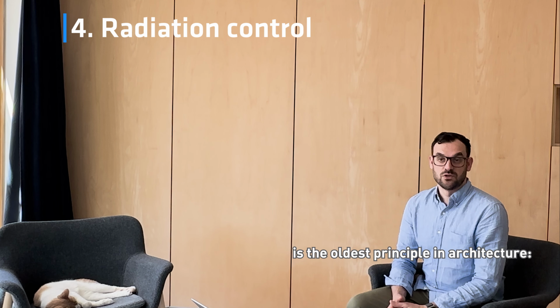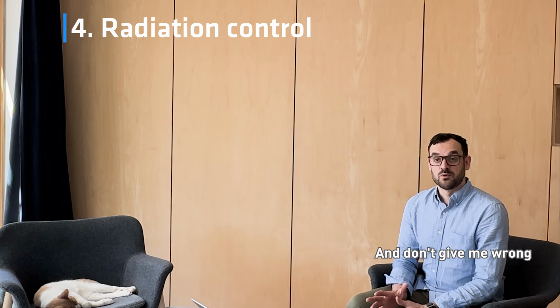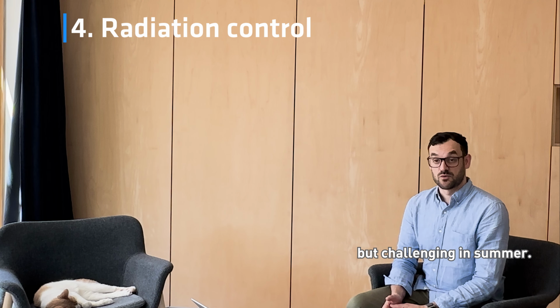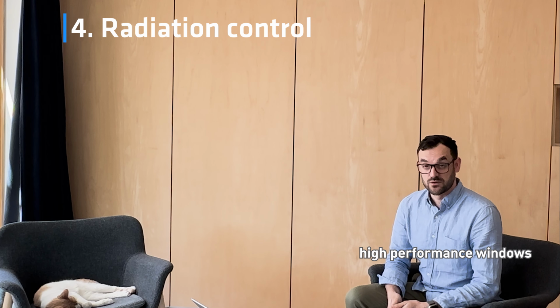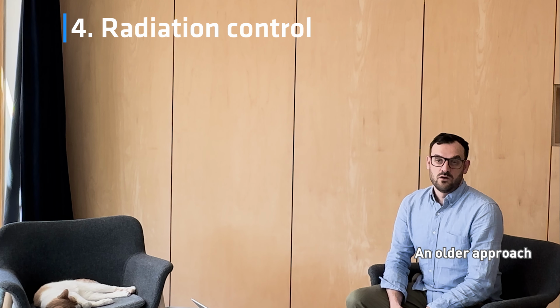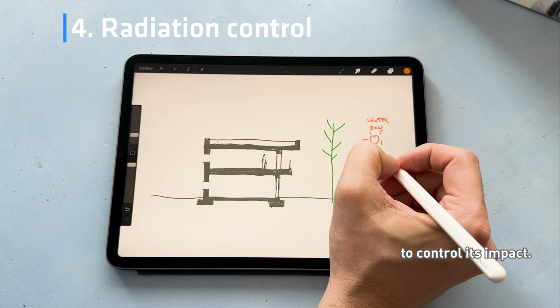The fourth one is the oldest principle in architecture, radiation control. And don't get me wrong, when I say radiation, I'm talking about the sun. It is a major source of heat that is useful in winter, but challenging in summer. One way to address its impact is to install high-performance windows with highly efficient glazing that contribute to the building's insulation barrier. An older approach, dating back centuries, is adjusting the house orientation to the sun path to control its impact.